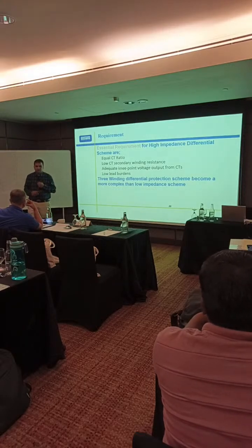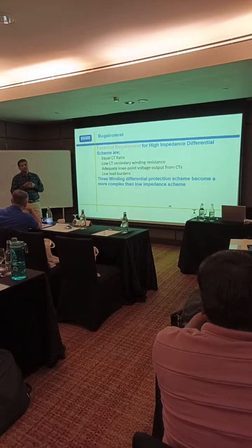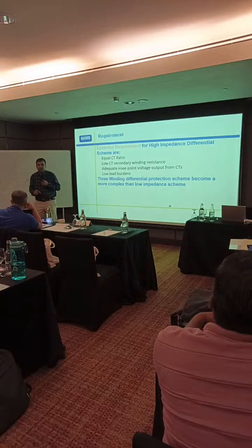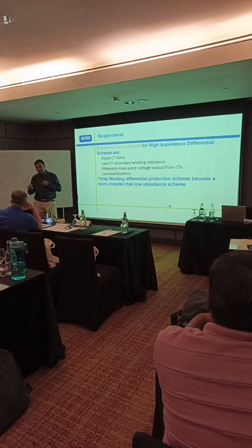How do you verify the Metrosil, whether it is still okay or not, because we just leave it there? It is recommended by the relay manufacturer. If you go through the manual, you can easily find how much resistance it should be.